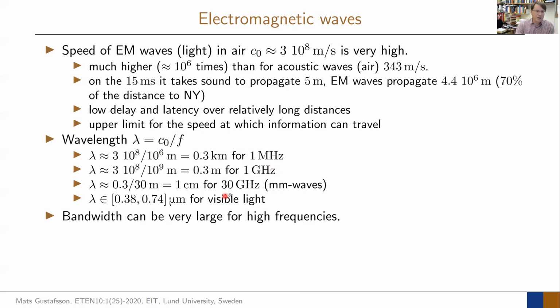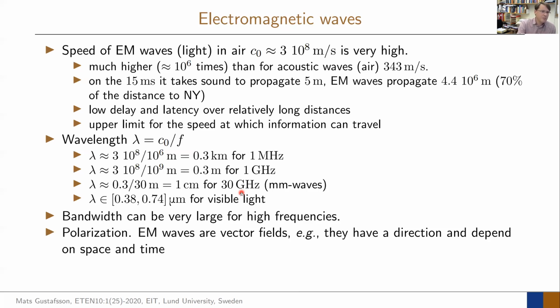But if you take 1 megahertz around 30 gigahertz, it's basically nothing. It's extremely narrow band, but it's the same absolute bandwidth. So when you go higher and higher in frequency, you have more and more bandwidth available, which means you can have higher data rates, which is one of the things that comes in 5G when we come to millimeter waves, because we go up so high in frequency, so we have a lot of spectrum up there.